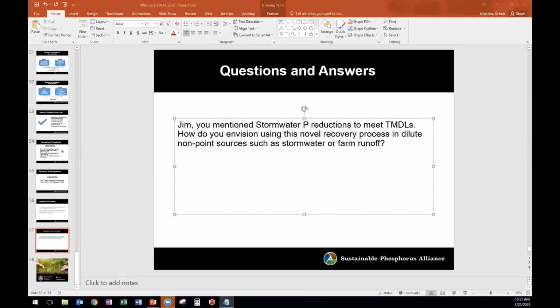Because of that, we are now applying the treated biosolids with total soluble P as a limiting factor, so our application rates have gone down in order for the farm to comply with their agricultural practices. So number one, we're using this process to reduce the amount of P that we're recycling back into the environment as biosolids and getting it out of the Lake Champlain Basin, or at least out of the areas where we have a higher P number.